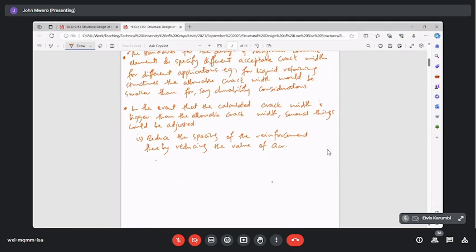And I have here with me an example, this problem that we have looked at. We were working with T20s at 125 centers. We could say, why don't we try T20 at 100 centers? So SCR reduces, but then the reinforcement increases, so it becomes less economical. Or you could say, let's try T16s at 100 centers. This is not a very good example, but if we could reduce the reinforcement size and the spacing such that we achieve a similar amount of reinforcement, then that would be a good solution.